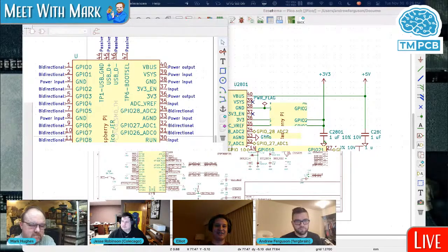I used EasyEDA before, and if you put a resistor in line with something, the net names will make sense. If you go from a pin to the resistor to some other passive, and then the passive to something else, it'll maintain a meaningful net name throughout. But here you kind of lose all semblance of that, and labeling every single segment between components with a name is unfortunate. I will say I used to not label my nets as much, but I found it is helpful